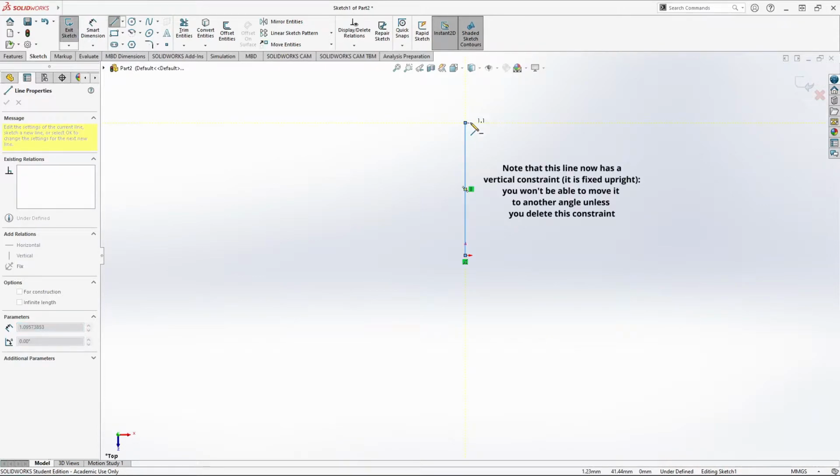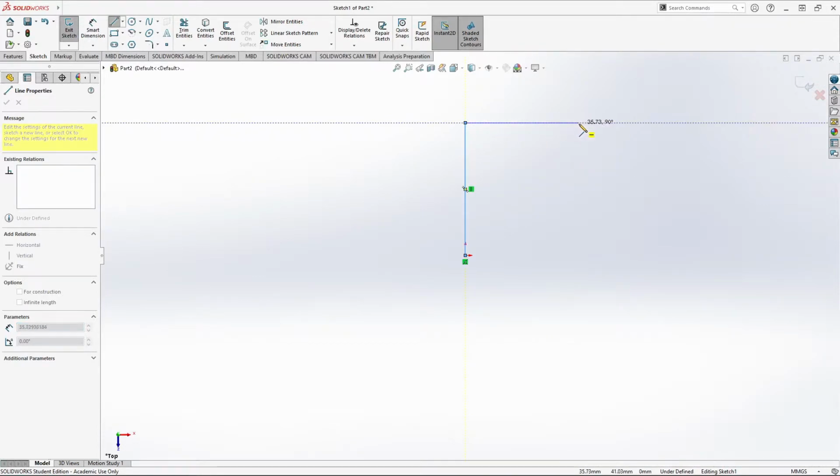Now we're making a square, so we just go over to the side here, click, and go down, and then you click again, and as you can see, it's showing this construction line. So when it shows this kind of dotted line going over to the left here, it's identified that maybe you want to place this point on the same kind of vertical level as the origin, which is exactly what we want to do.